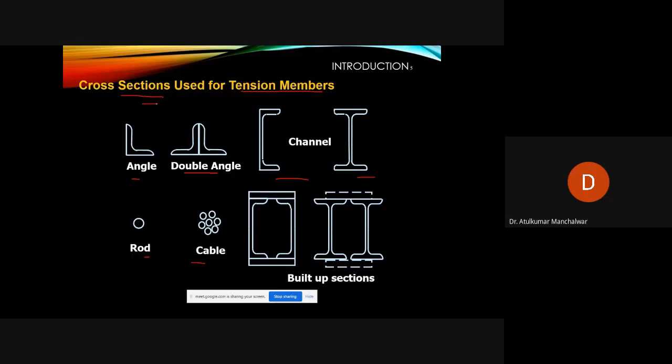if it is a truss, these two are preferred in trusses. Okay, this I section is very rarely used. If in any examination a question comes on which type of cross section is used for the tension member in trusses, you should mark angle section, which is confirmed to be used in truss sections.